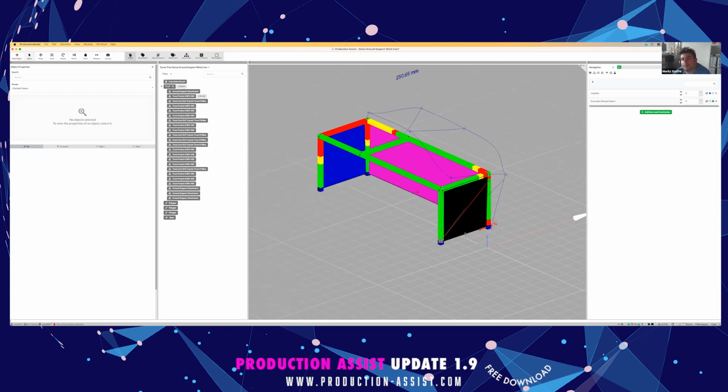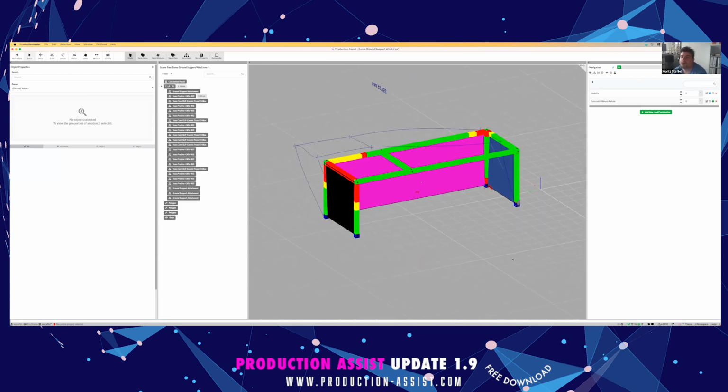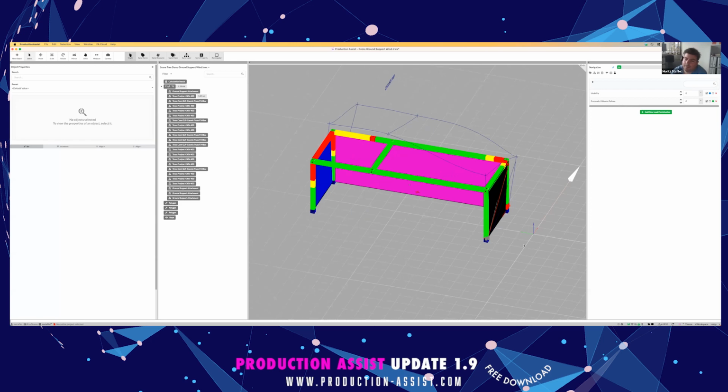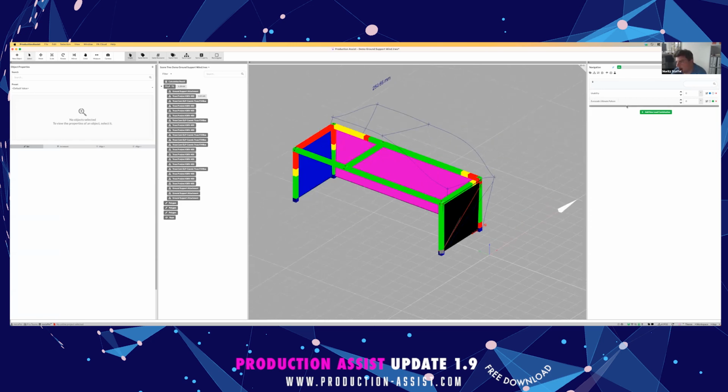We will have a look at the parameters that actually define your wind load calculation. The first thing in the load case is the direction the wind is coming from. So if you go to 45, it will come from this direction. If you go to 90, it will come into this direction and also blow in this direction.